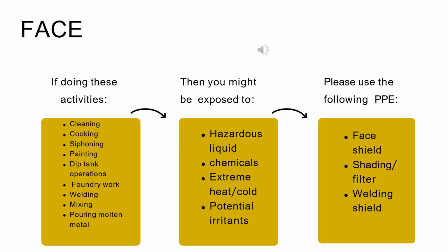If you are doing these activities: cleaning, cooking, siphoning, painting, deep tank operations, foundry work, welding, mixing, pouring molten metal, then you might be exposed to hazardous liquid, chemicals, extreme heat, cold, potential irritants. Please use the following PPE: face shield, shading filter, welding shield.